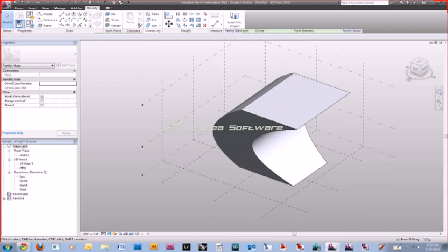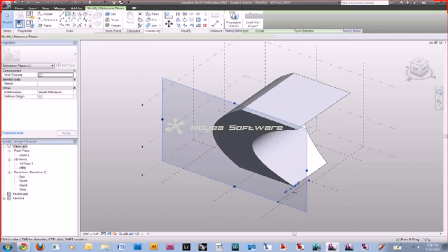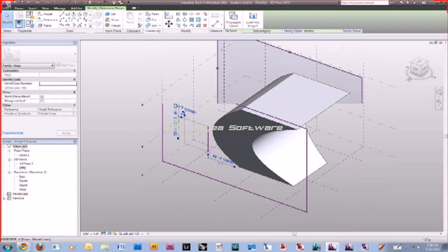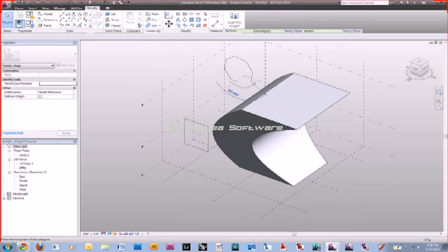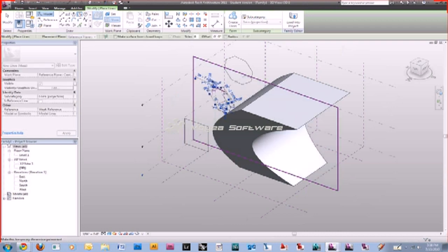Can the shapes be on horizontal and vertical planes? All right, so let's say that we want to do a loft this way, so I can select this plane. It just depends on what planes you choose. If I select this plane here, I can go ahead and make a rectangle on this one, and then I hit escape, and then I go to this plane and create another shape, let's say this pentagon, and then I go to this reference plane and create another one, and then I select those three shapes the same way we made the other loft.